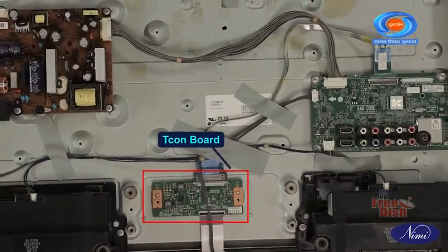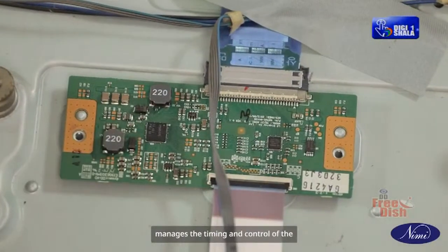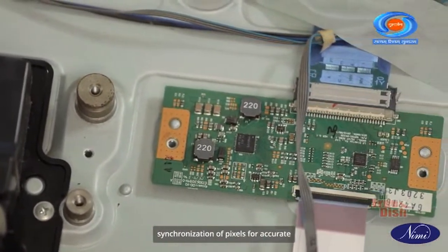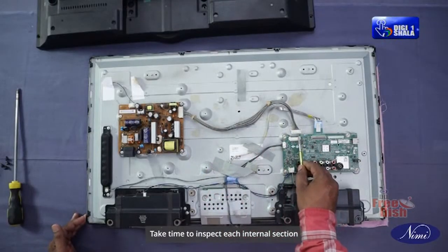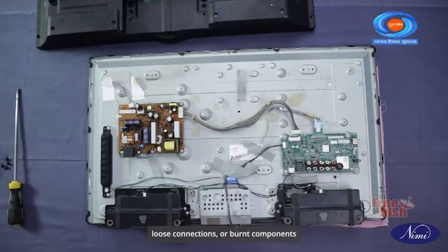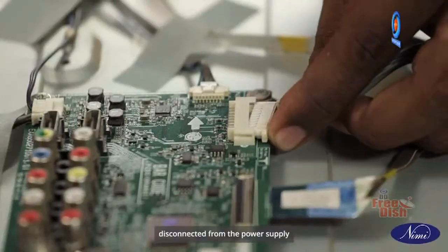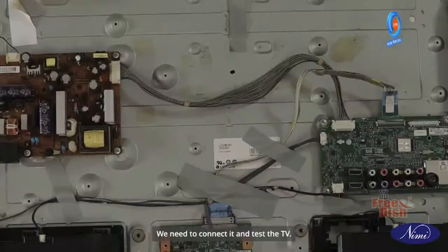T-con board. Typically placed at the top center or back of the TV, this board manages the timing and control of the display panel, ensuring proper synchronization of pixels for accurate image reproduction. Take time to inspect each internal section carefully, looking for any signs of damage, loose connections, or burnt components that may indicate a fault. As you can see here, there is a cable disconnected from the power supply to the main board. We need to connect it and test the TV.